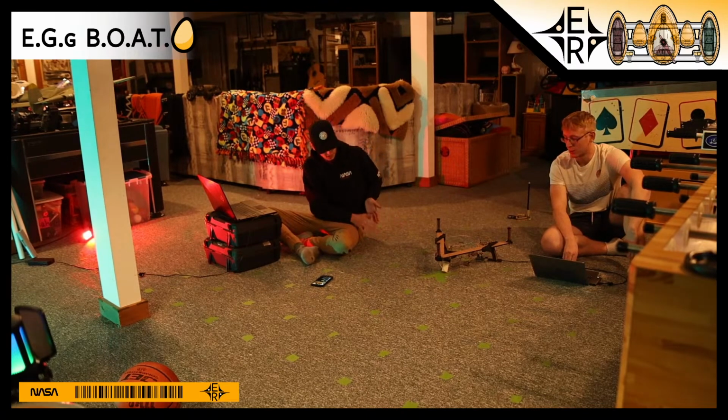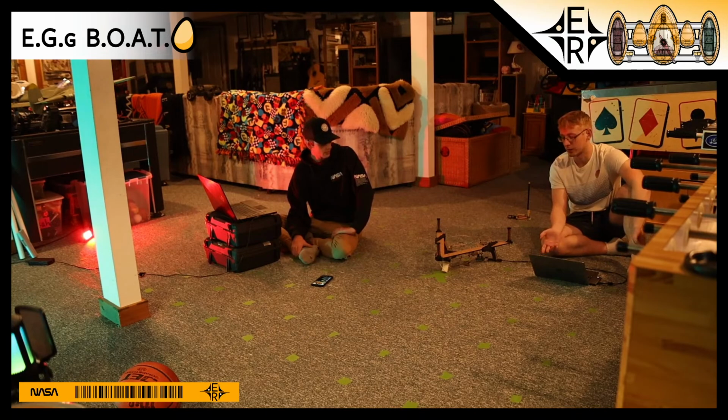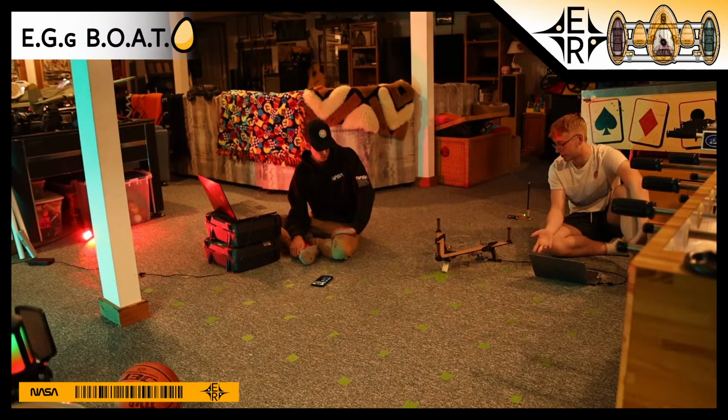And phase 3 was the initial development of the phase comparison. We didn't need the beacon for this. This was just trying to figure out how the circuit would work on an individual basis. First, we needed to make sure we could get the variable amplitude, depending on distance, of the received AC signal. We needed to make sure we could get it to a square wave. We needed to make sure that the phase comparison topology would work in general, so I was prototyping at lower speeds on a breadboard. That's what I was doing for most of phase 3, and I didn't need the antenna or the beacon for that, which was fine.